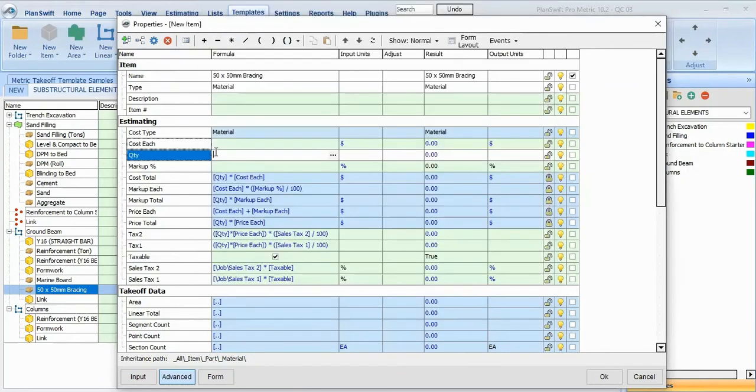Under this quantity, we'll be needing 4 number of our plank, the one that will be on the perimeter of our column. Let's assume the spacing of that is 300 mm. So let me link the total quantity for my formwork to this place.